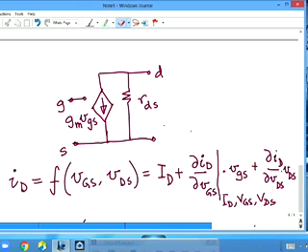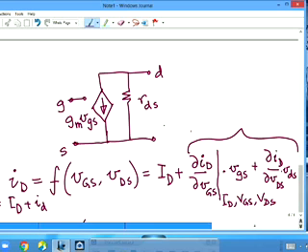So this is small signal. These are the first order terms, and then you've got second order terms in your Taylor series, and so on and so forth. If you now say that small vgs and small vds are infinitesimally small, then only the first order terms remain. The second order terms and so on can be ignored. And therefore the incremental small signal, which is small id riding on top of capital ID, is just these portions. Capital ID goes away.